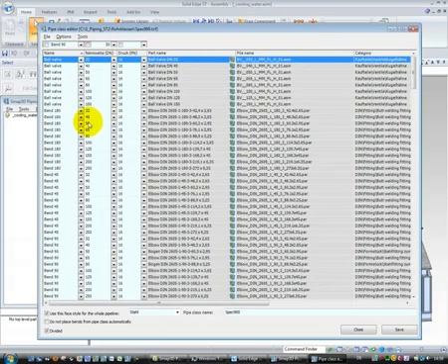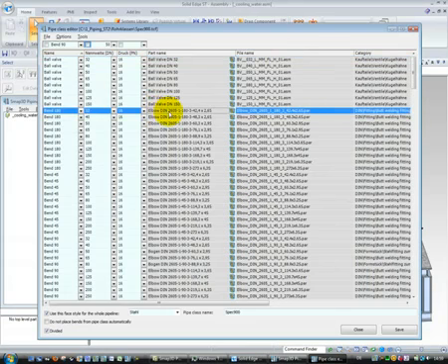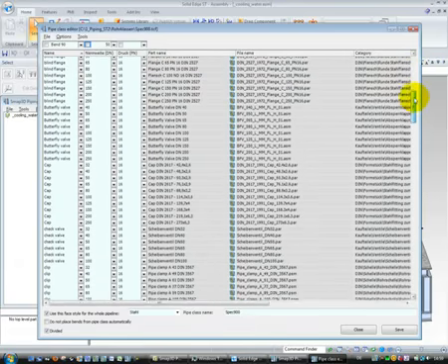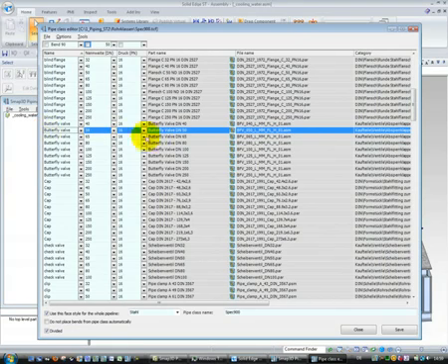Like I explained before, in such a pipe class there is a specification from one specific 3D model to one specific situation, which is used for an automatic creation of a 3D pipeline. But in such a pipe class there is also the possibility to specify and define components which cannot be used fully automatically, but where the definition makes sense to use it interactively, in a kind of manual communication between the software and the user, to place it easily and fast and process secure from the pipe class into